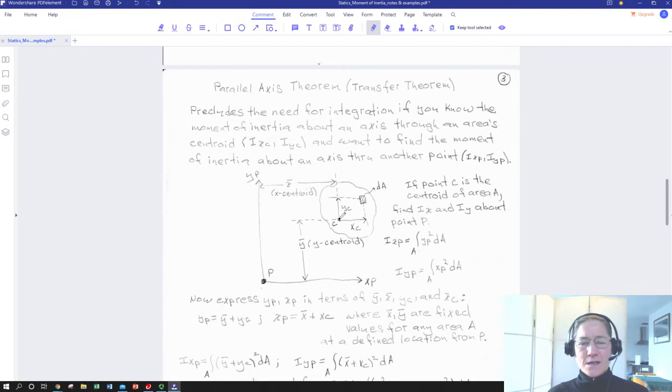Okay. Typically, we will have already defined in a lot of cases the moment of inertia around the centroid with respect to both axes and maybe the polar moment of inertia as well. We did this for a triangle, we did it for a circle. You'll find as you go on in your studies, there's lookup tables for standard shapes where somebody has already done the integration and then wrote down the results in terms of the dimensions of your shape and which axis you're talking about.